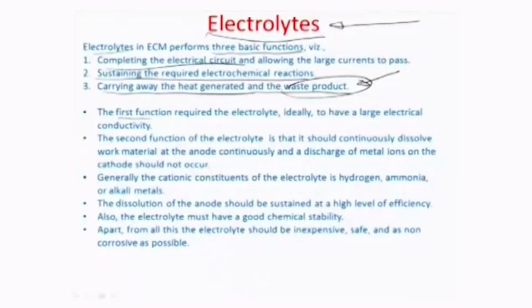So, what are the requirements? The first function requires that the electrolyte be of large electrical conductivity, and the second function requires that it should continuously dissolve work material at the anode. So, it should sustain the electrochemical reaction at the anode. The anode is the workpiece in this particular case, and it should discharge